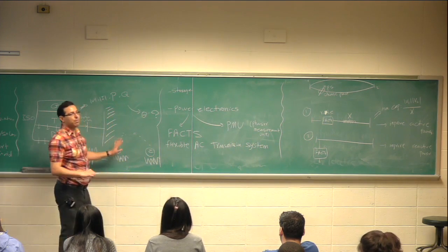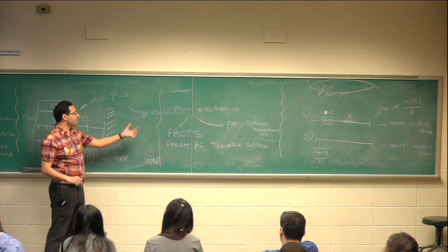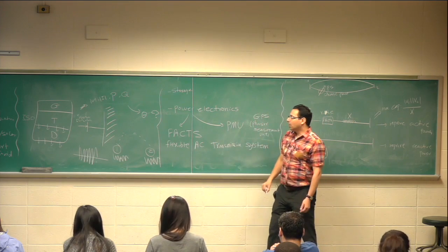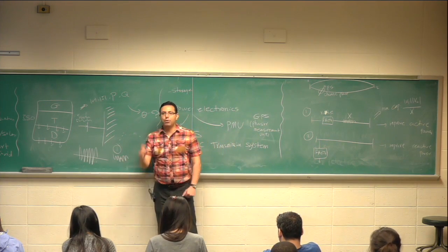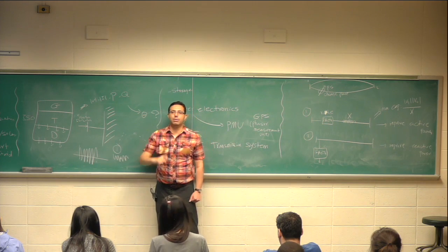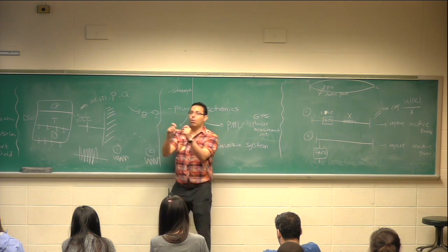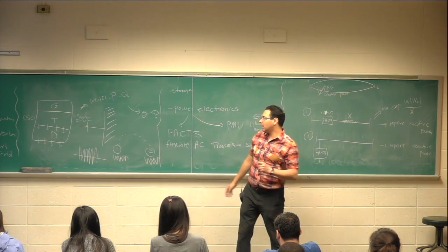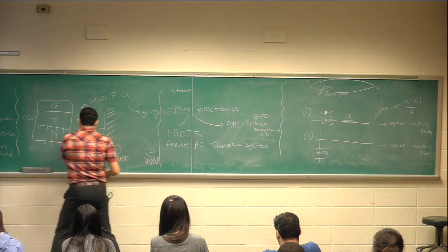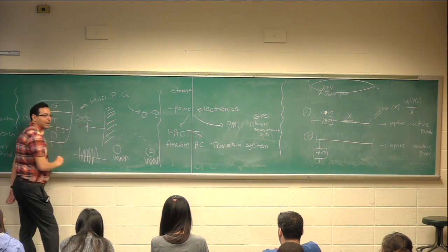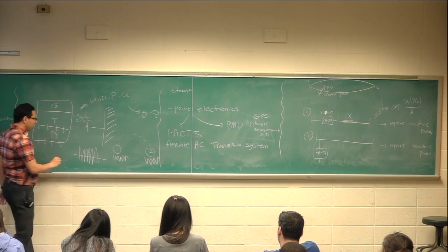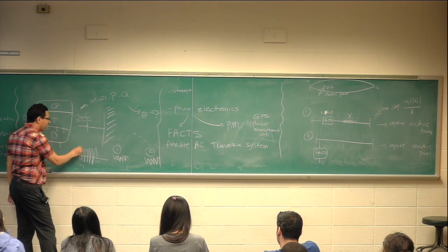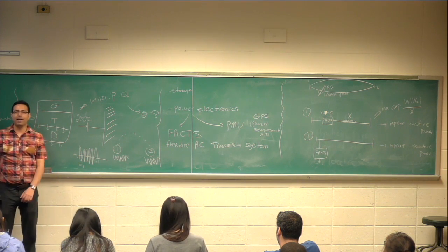Years ago, it was impossible to do this. Now each PMU has GPS, global positioning system. So whenever they measure something, they put a timestamp coming out of GPS. They would say, I measured this signal according to the timestamp that I got from 4 satellites of GPS. Then here we talk about delay. Delay is really important. This is 1 second. If someone gives me 100 milliseconds of delay, I can go from 1 max to 1 min. So delay is very sensitive.